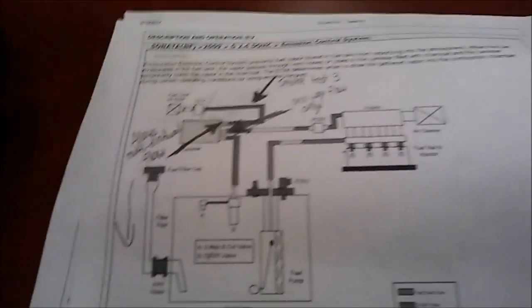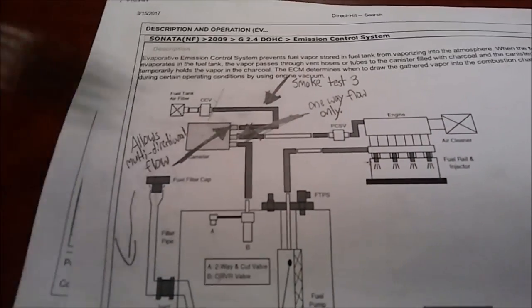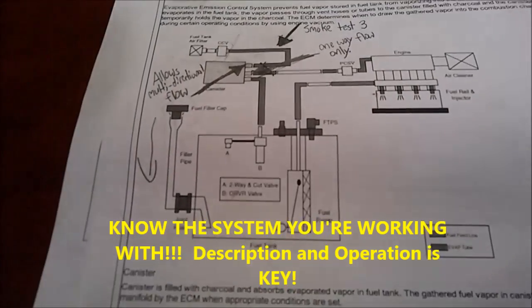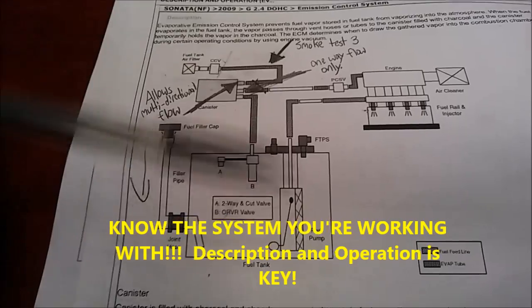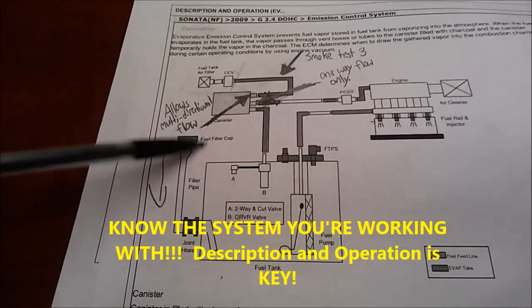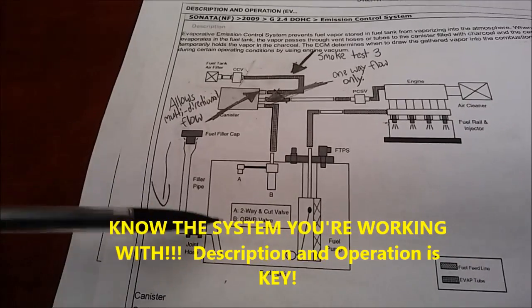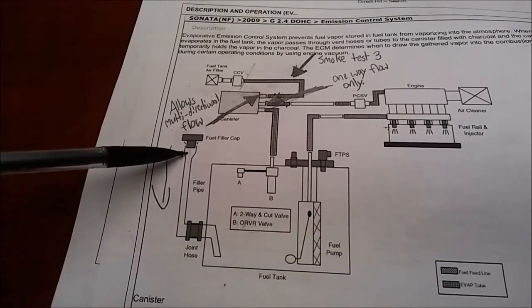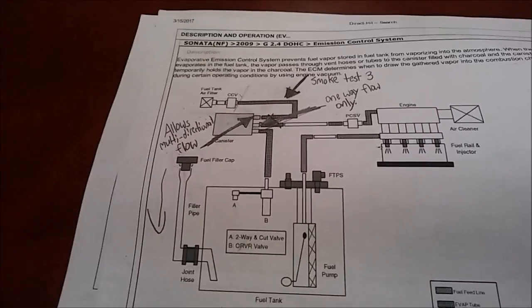So yeah, definitely some variables to this. Don't think you're just going to hook up to the purge solenoid on every car and get smoke all throughout the system. It's absolutely not the case. We definitely need to be aware of what we're working with, and I routinely check to make sure I have smoke from this filler cap. And that's the only way that we really saw this issue, was the visual inspection there to see if we actually had a full system or not.